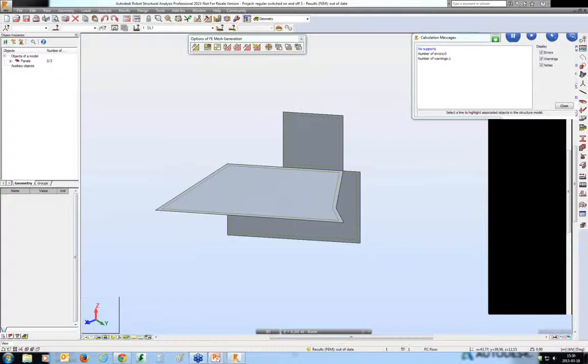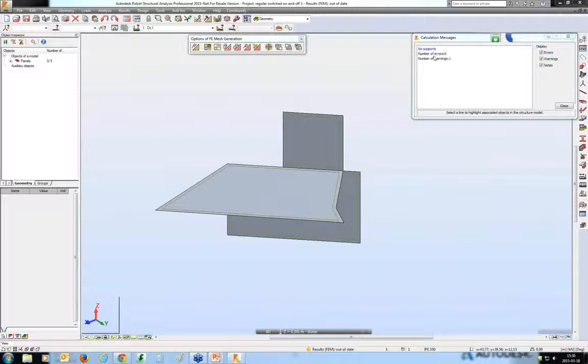My assumption is that you have an incorrect analytical model in Revit, which causes issues with meshes in Robot. So first I would just correct this analytical model using this detailed correction option to structural axis.